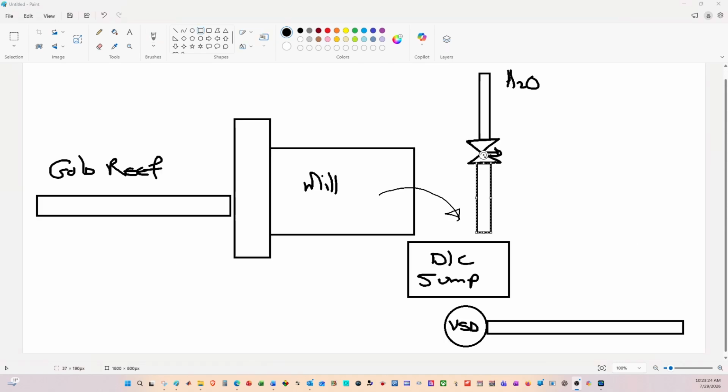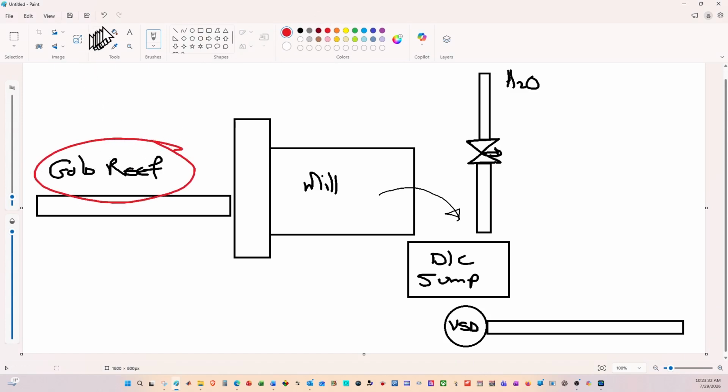Here's another real world example, and one that I've actually seen in the past. Imagine if you were to have gold bearing reef that you bring in from your gold mine itself, and you put that into the mill. Now that is a rotating mill. It's got steel balls on the inside, and as it rotates, it crushes the ore up to the point where you can have a slurry that comes out of the mill, and that goes into a discharge tank.